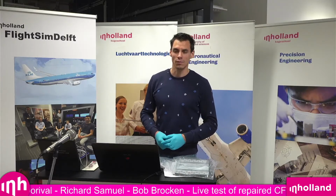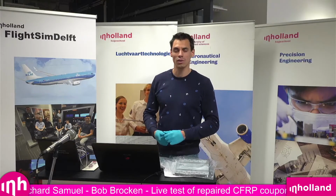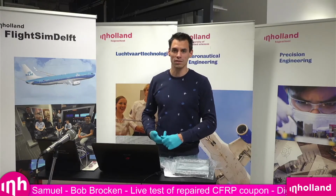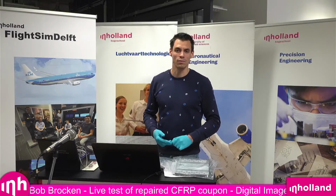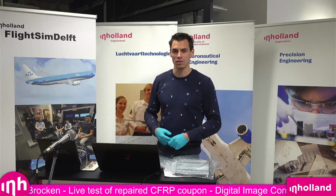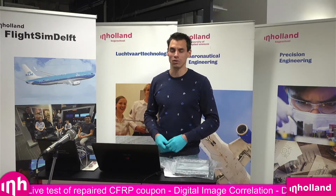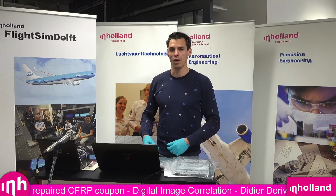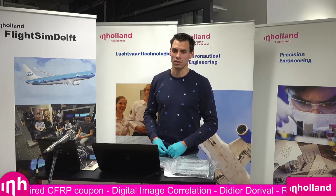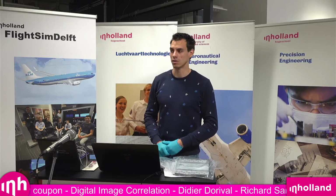Procedures are described in the standard for an extensometer, how to calibrate it, for strain gauges, what sort of requirements they should meet, and also for an optical device such as a DIC system. So a certified institute could also certify this DIC method to comply with the ISO 9513 standard. So it should be possible even for the aerospace industry.